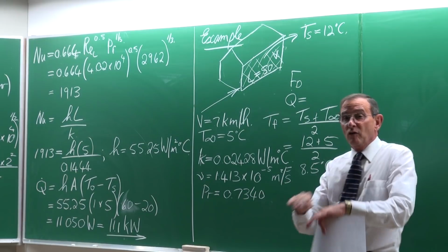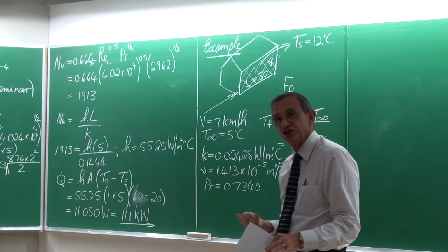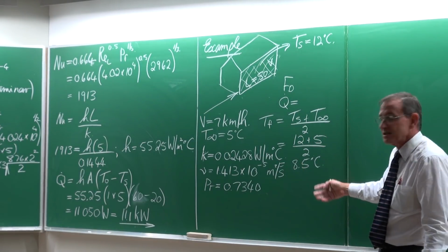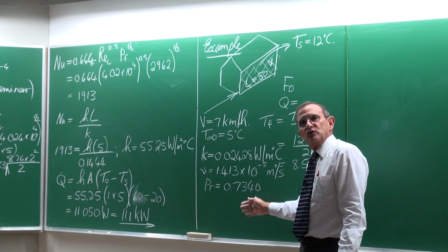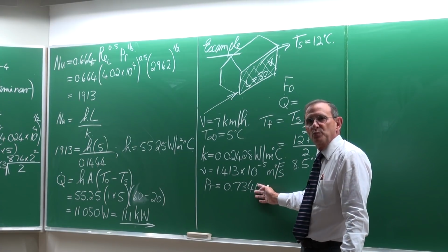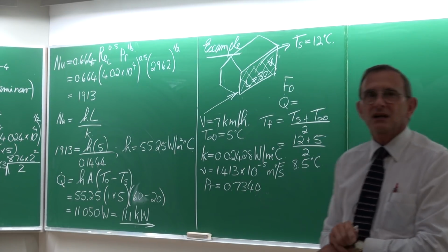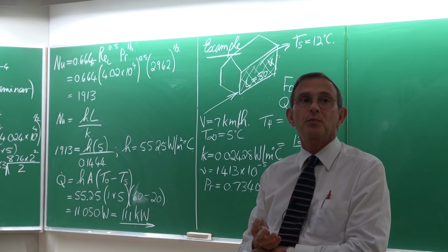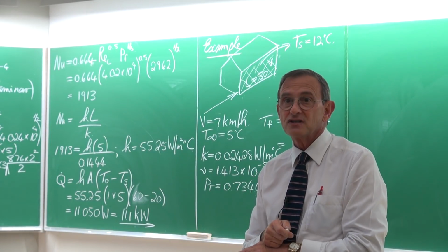Okay, so if I remember correctly, typically many of the derivations have been done with a Prandtl number of 1. It makes things so much easier. And then they've tested it experimentally for other Prandtl numbers, and for most gases, their Prandtl numbers go down to about 0.6, air also about 0.6. So in general, most of the gases are also fine with the equations. It's just when you start getting to things like liquid metals, mercury, for example, then you've got another set of equations that you need to use specifically for them.